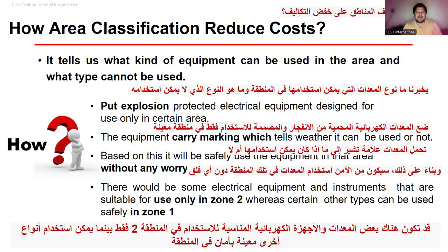No, no, no. You purchase equipment compatible with zone 22 for combustible dust, and you are thinking you can use the same equipment in zone 20 also. So, guys, your procurement strategy should also be based on this classification. So, this classification is truly important.